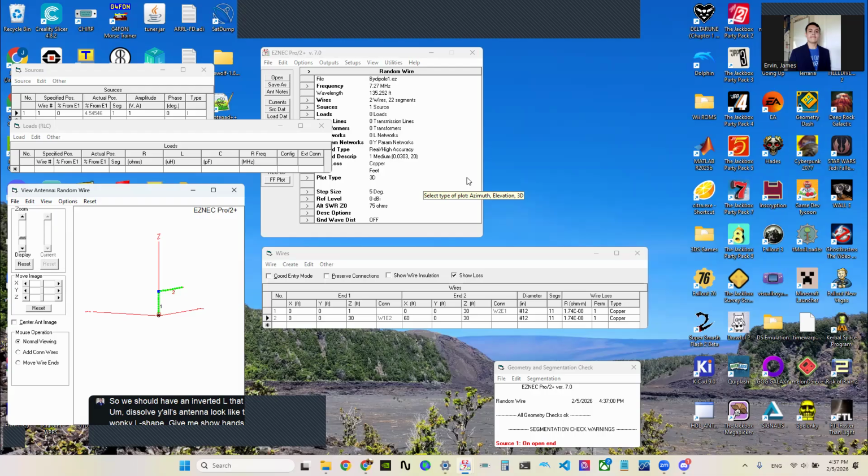Right now I'm on... Okay, do you have your first wire defined as going from 1 foot to 30 foot, and then another one going from 30 foot to like 60 feet over, still at the same 30 feet of elevation? Yeah. Your thing does not quite look like an inverted L. Yeah. So it should go from a Z of 30 feet over 60 feet in the X direction, and then a Z of 30 feet. So say you got two poles or two trees in your backyard, you just run a wire up and you run it across. Cool. All right.